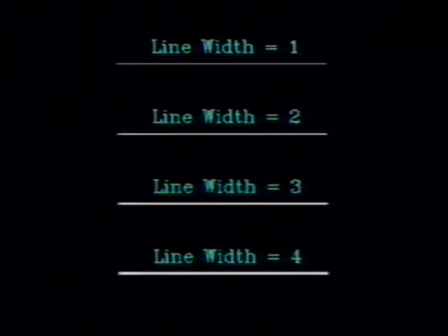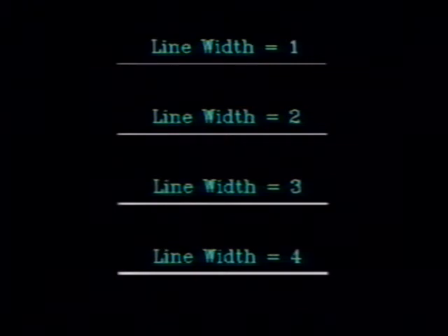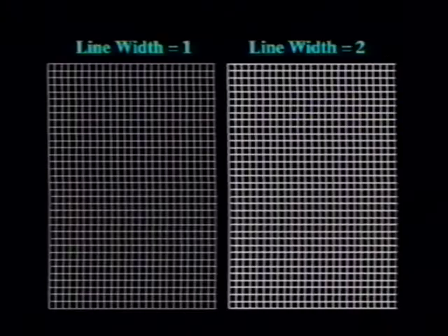With interlace scanning, an electron beam scans horizontally across the screen and displays odd-numbered lines on one pass and even-numbered lines on the next. Therefore, lines that are only 1 pixel wide are only displayed on every other pass, which we perceive as line flicker. This problem is especially obvious when several horizontal lines are displayed together as in these example grids.